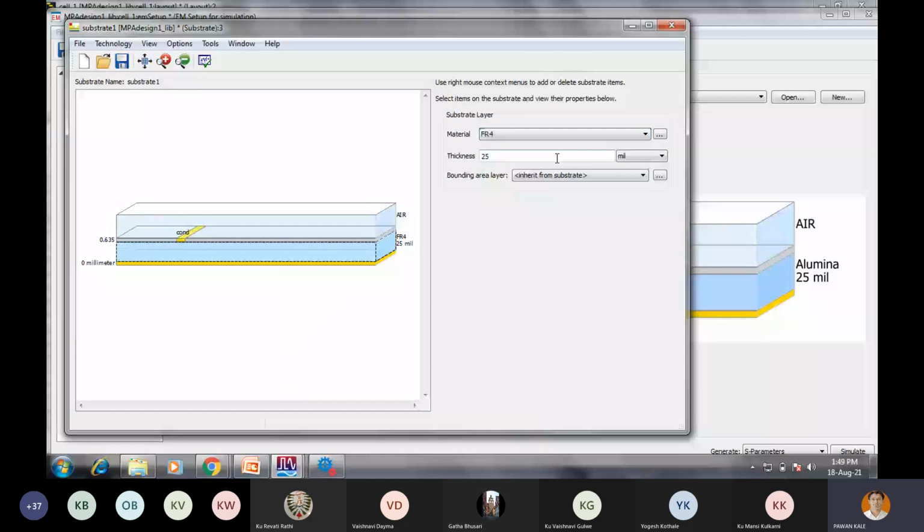हाँ, इसकी जो थिकनेस रहती है FR4 substrate की, ये रहती है 1.5 mm. So अब देखो यहाँ पे ये जो दिख रहा है ना आपको, 1.5 mm की थिकनेस दिख रही होगी FR4. ओके, मिलीमीटर लेना है हमें. सो इट्स 1.5 mm. देखो ये FR4 सबस्ट्रेट है जिसकी हाइट कितनी है, 1.5 mm थिकनेस. ये ऊपर का पैच है और नीचे का ग्राउंड.